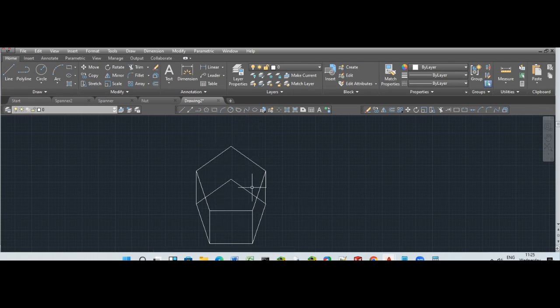Now I'm going to trim inside. That's what I'm going to do. So I'm going to go to trim, click trim here, then click this shape, press Enter, then click this, then click this. I press Enter. So you see you have something already beautiful looking at me here. So now the next thing to do, I'm going to put a circle inside this. So I click a circle here, come to the middle of this knot here, click in the middle here, draw it to an appropriate size, and I press click. So you see it beautiful.